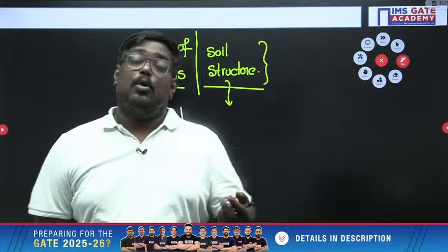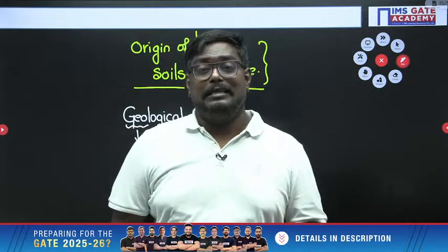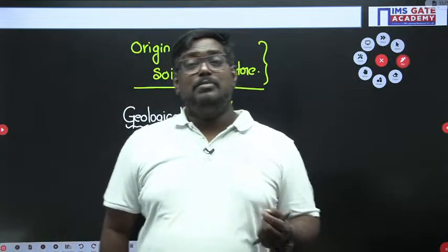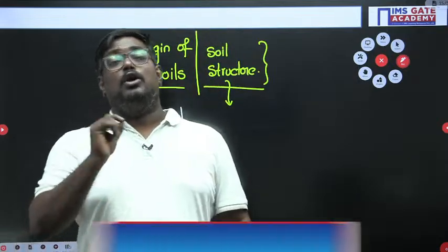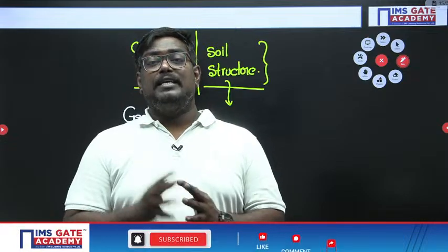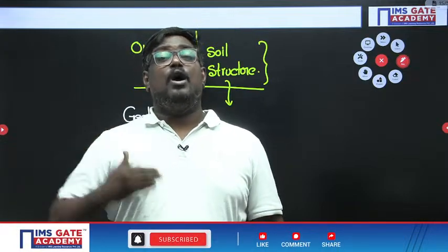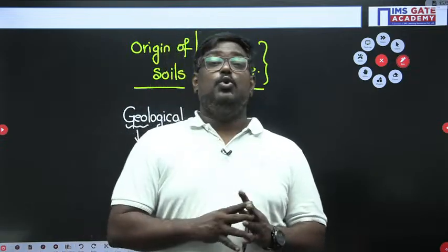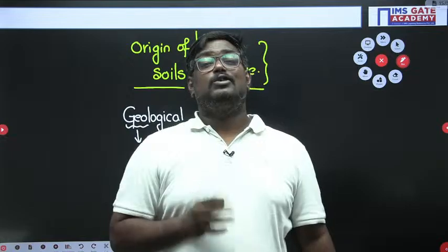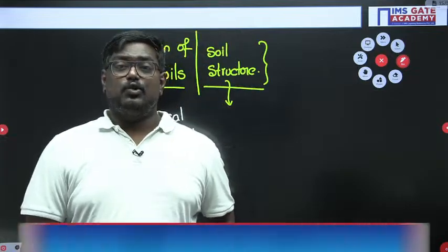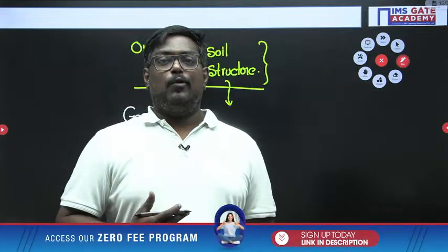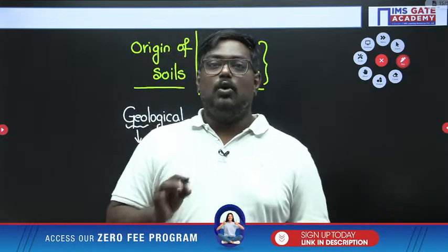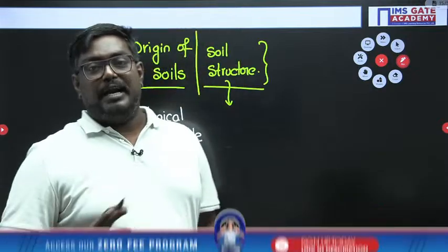Now there is a property in soil like elasticity, but we should not call it elasticity, it is a kind of property. We have a term, and you are also aware, called thixotropy. What do you mean by thixotropy, sir? The phenomenon of regain of lost strength with the passage of time with no change in water content is called thixotropy, which you might be clear.